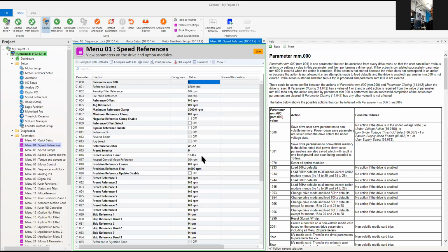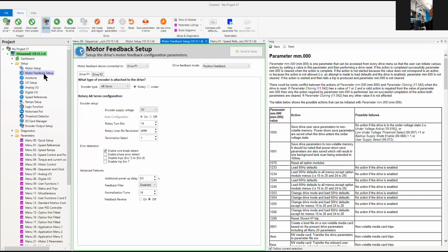What you need to consider is, you remember if I change the order of A1, A2, A3, the motor might go in the other direction. What does it mean? If the motor feedback is set up, there is a chance the feedback is reversed. I just double check that one to see why it didn't work.